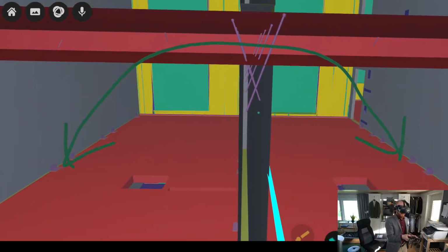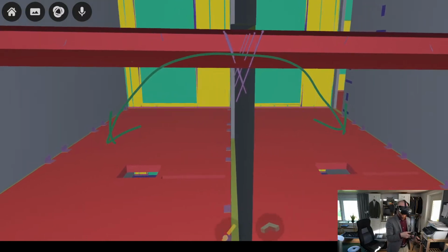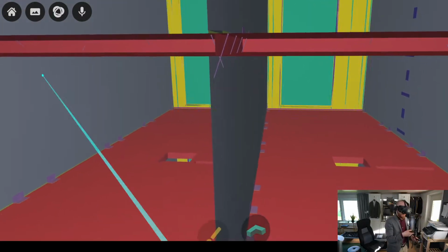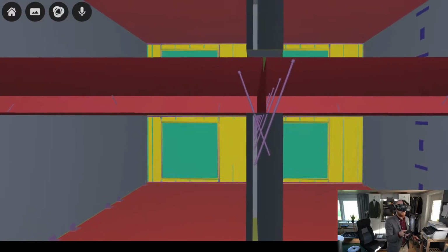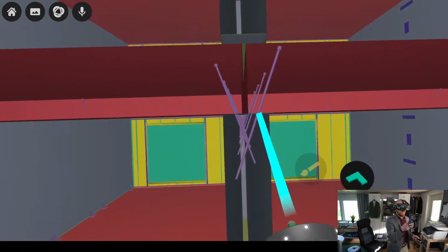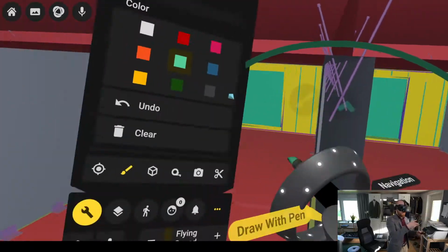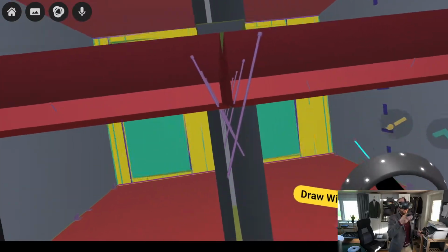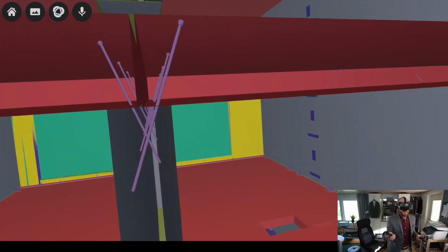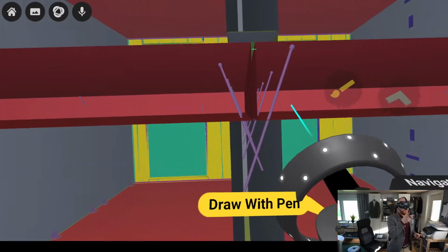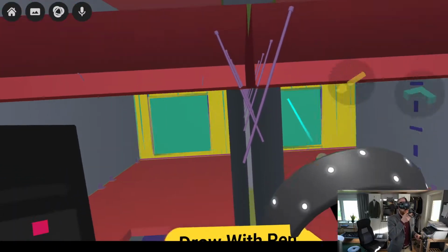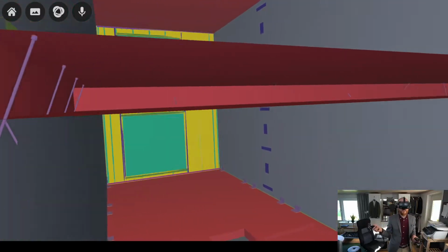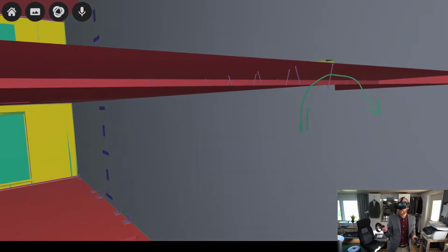And this is a very sensitive flanking transmission path. When you're looking at this type of connection instead, the sound cannot travel like this because there's a slice in here and it's stopped. But if you're going to do like this on every single apartment, you're going to get a lot more CLT elements that the crane will have to lift and mount. So it's going to require a lot more time.